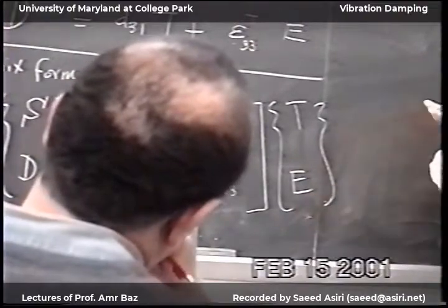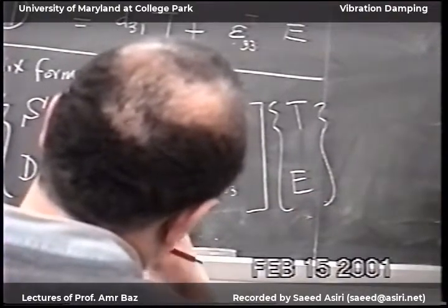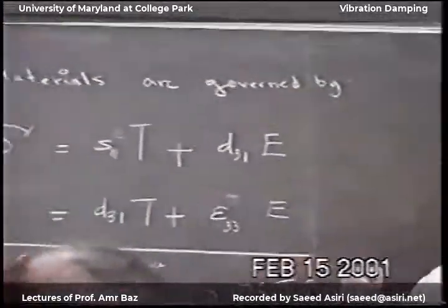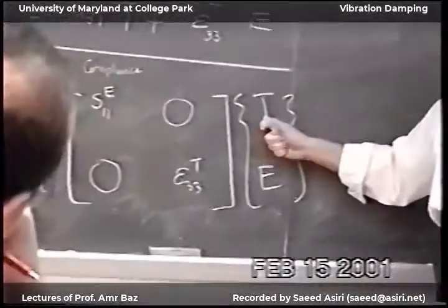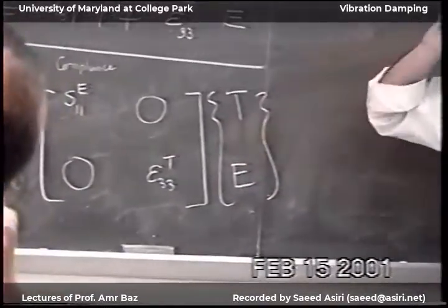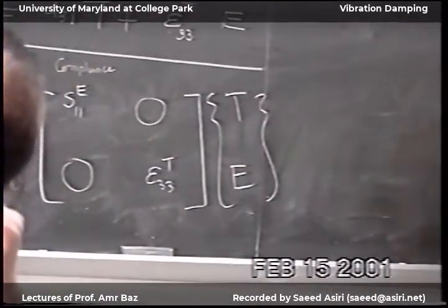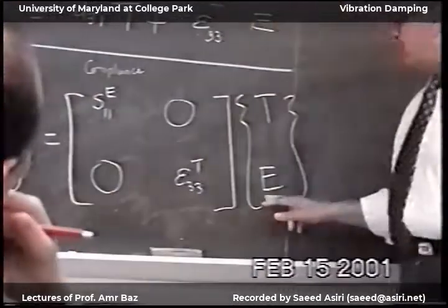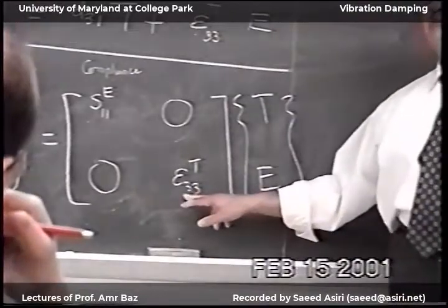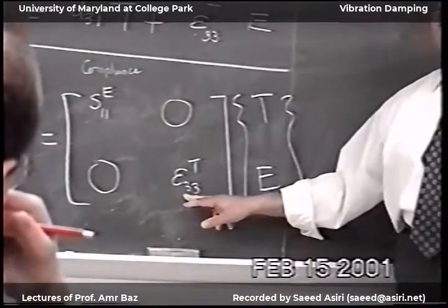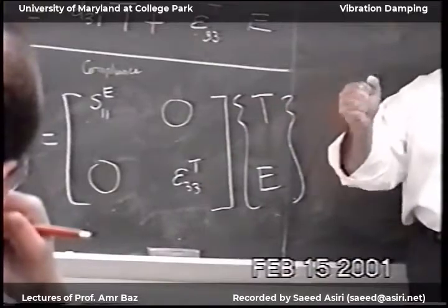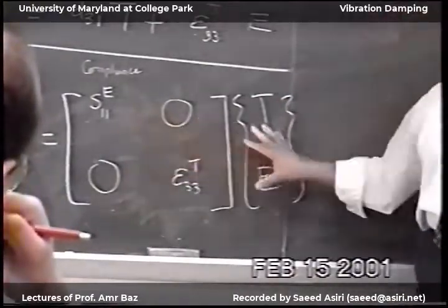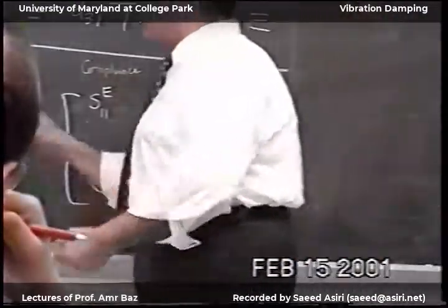If I apply electric voltage on a piece of steel, it will not expand or contract. The steel will expand or contract only if I apply a mechanical load on it, stress. In the piece of steel, I can generate current through it by applying voltage, depending on this permeability term. I cannot generate current in the piece of steel by applying stress. So conventional materials are like this. So in a matrix form, for conventional material.